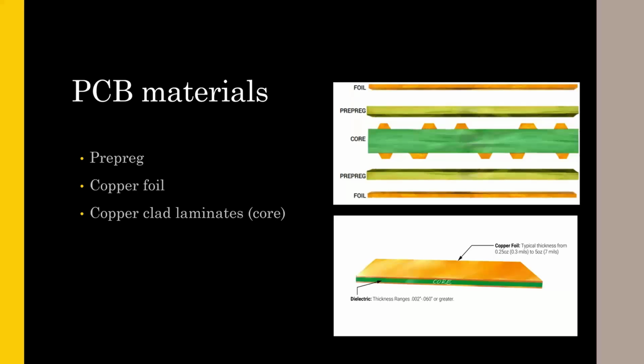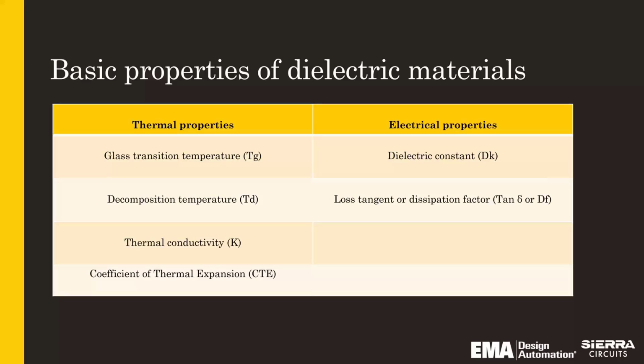And we'll go into the next slide, which is like, what are the ingredients for PCB stack-ups and PCB materials? So it starts off with pre-preg, copper foils and core materials. All are important in your design considerations. So pre-preg is B-stage material that is tacky and allows for bonding of the different foils or laminates. A copper foil is, obviously, for your traces and your pads. And then your core material basically is pre-preg that is already melted or C-stage, and there's copper foils already laminated to that core. So all those are very important ingredients to your stack-up, as we'll talk about later.